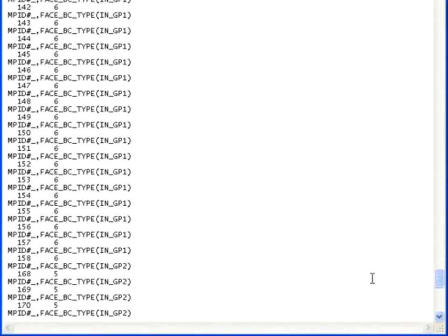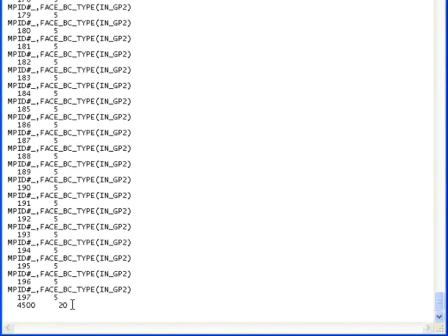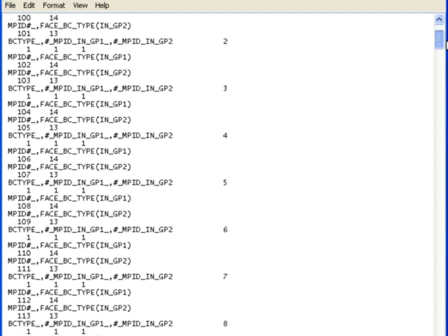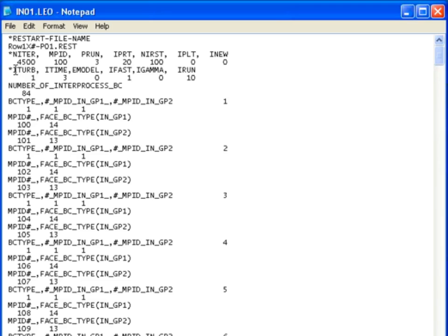One thing to note when doing unsteady simulation is that at the end, the inner iterations and the iterations per cycle are placed here. If you would like to change them, you should change them now in order to set them to settings you are more comfortable with. So you can see our per cycle iteration is 4,500, which is equivalent to the number of iterations in total we are running. So we are running one full wheel.